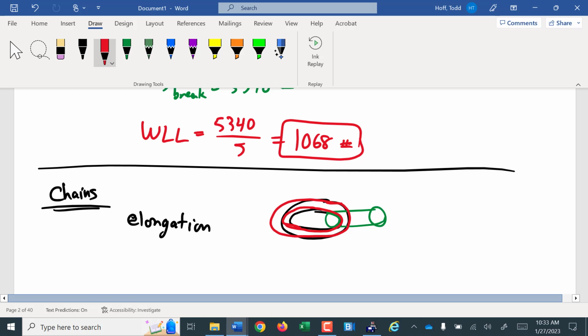Downstairs in room 134, one of the rooms you sometimes use, I have an old tensile tester. I used to do a material engineering course for machine tool, where we would stretch specimens until they broke. And you could see for stainless steel especially, an 1/8 inch diameter round piece of stainless steel that starts out at 3 inches long, we could actually stretch it over 1/4 of an inch before it broke. But it went from an eighth of an inch thick down to just over a 1/16 of an inch thick before it snapped, because as it stretched, it has to get thinner. It's called necking.